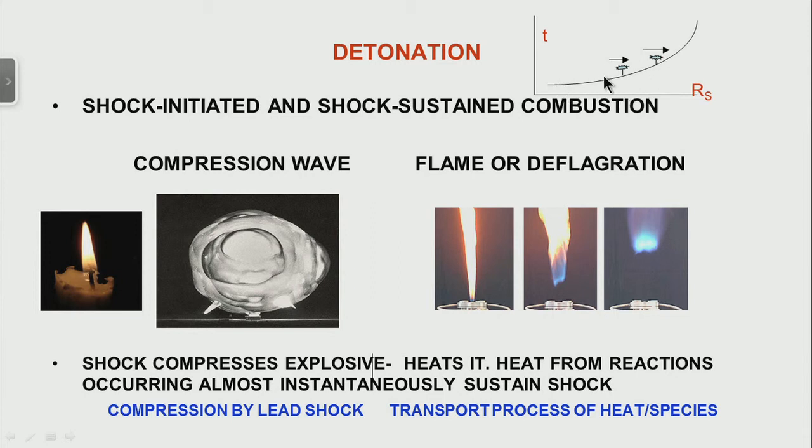If the temperature behind the wave is quite high, the pressure is already high behind a blast wave, and now the temperature is high. Therefore, I have something like a compression. Instead of having an expansion in a flame, I have a compression, a huge compressed type of gases being formed, and this shock compressed explosive, or shock compressed movement of the flame front, is what is referred to as a detonation.